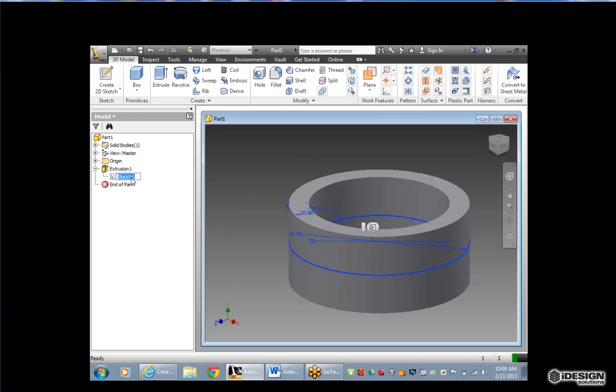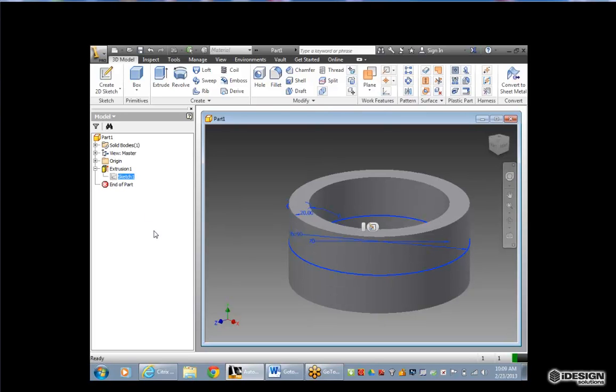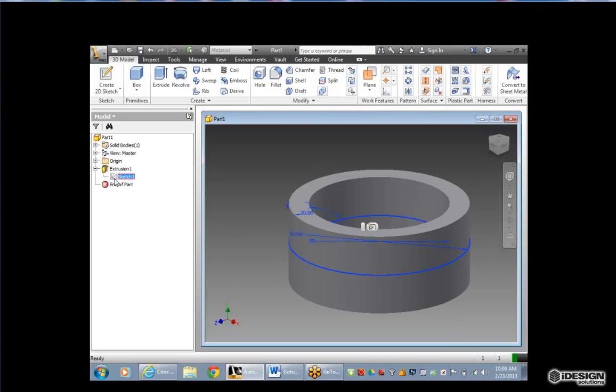And how do I share that? Oh, you just hit escape. Right now that would be how you could rename it. You could rename that to original sketch or sketch number 1-2, whatever you like. Really, once your parts get a little bit more complex, you might actually want to name the features. So you just highlight the sketch and right click, and you'll see share sketch.